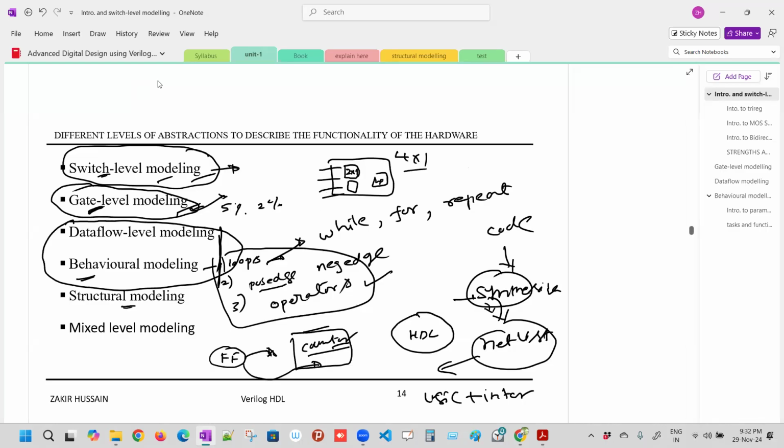Yes. Just now we discussed the half adder, and a full adder using two half adders. We are not actually generating the logic of the full adder. We are interconnecting the half adders in a way that can produce the full adder functionality. That is called structural modeling.